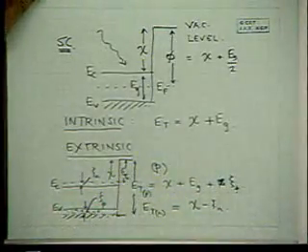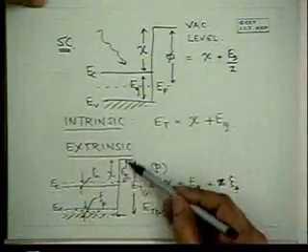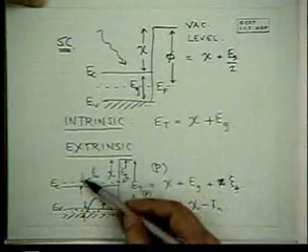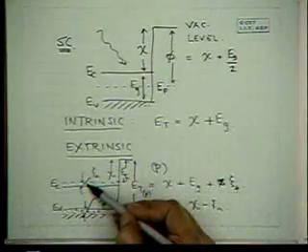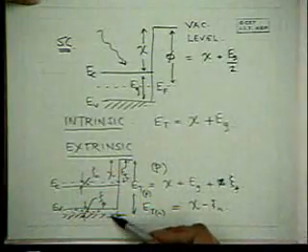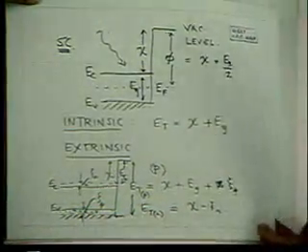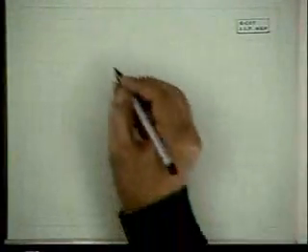However, although this looks attractive because you have reduced the threshold energy, remember, even for a very heavily doped n-type semiconductor, the concentration of electrons is only 10 to the power 18, 10 to the power 19, etc. Whereas in the valence band, the density of states is 10 to the power 22. So the question was, how can you reduce this threshold?